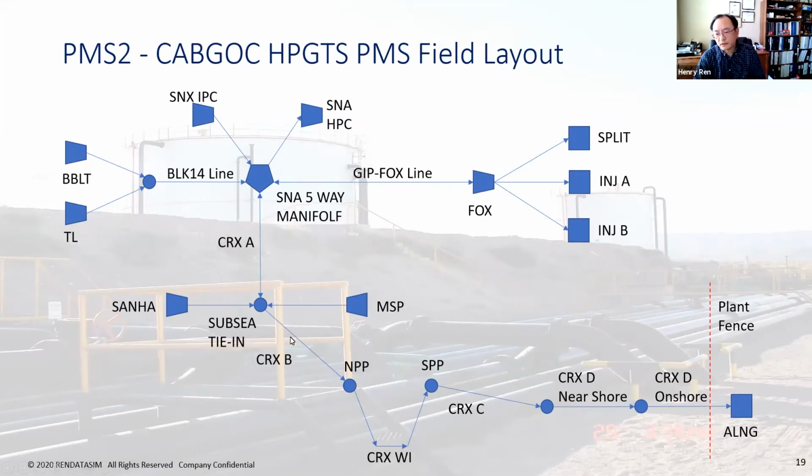This is 20-inch, 22-inch, and coming down here, the Congo River crossing. The river here goes deep, 1.5 kilometers. Basically, they drill the hole and connect the 11-inch pipe together. And then in here is 90 degree from 11-inch, then elbow, then it becomes 22-inch. And then here is 20-inch all the way to the onshore.